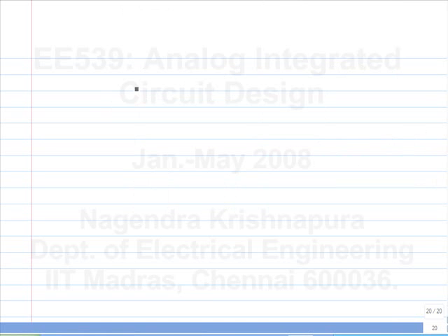So the next problem is very similar to this. In fact, if you somehow replicate this with MOS, although they are very different non-linearities, it turns out to have a very similar effect. Okay, it's not proportional to absolute temperature, but what did you get to be the transconductance of the MOS transistor? I mean, how was it related to R or was it related to many other things? It is inversely proportional to R. That's what you should have got. Let's quickly go through the analysis.